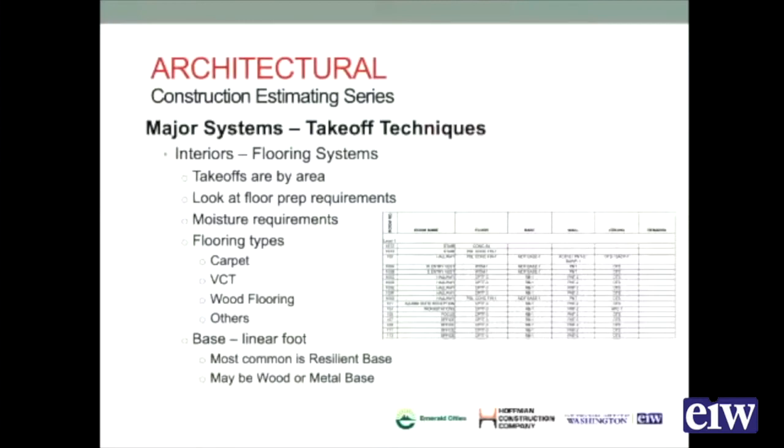When you're dealing with areas, typically everything is by square footage except for carpet, and carpet is typically square yards. So you need to understand that if you're acting more as a general contractor and you're getting a quote for the carpet, their price may very well be in price per square yard, not price per square foot. So you need to make sure that your takeoffs are coordinated when you're reviewing the bids.